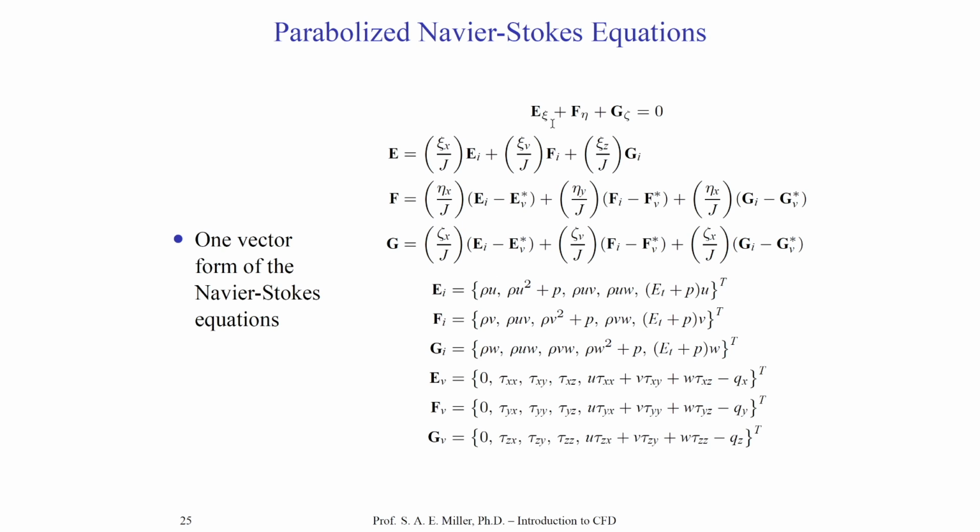So they're written in the metric notation, that is for a structured grid. You can also transform this for a finite element or finite volume approach if you do the mathematics. So what does this first equation mean? It's partial rho U partial psi, plus partial rho V partial eta, plus partial rho W partial zeta equals 0.